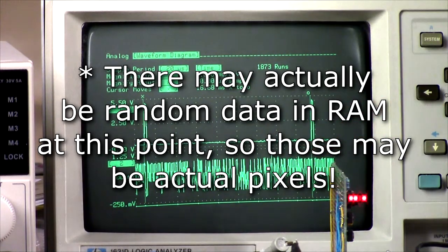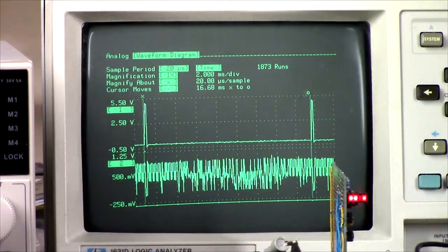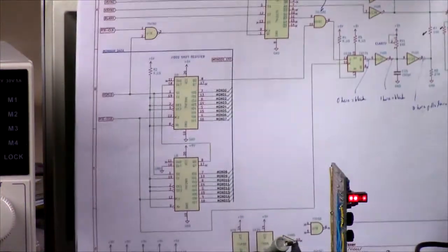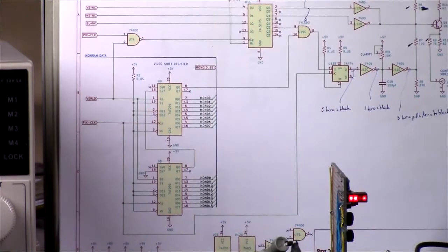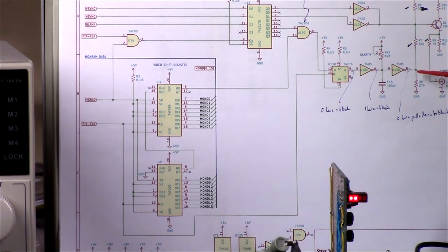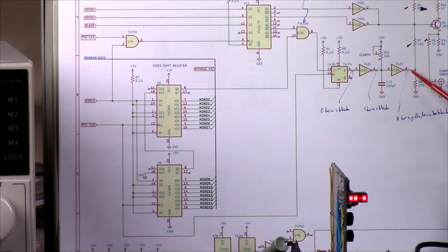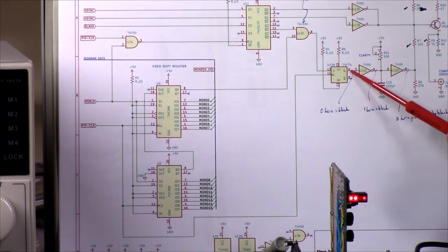Okay, speaking of black and white levels, we should be at black level, we're at white level. Why is that? Let's go back to the schematic. See that? Okay, let's see. This is 0 here pulls down to black level. So black would be a 0 here, which that's an inverter. So that means it's a 1 here. That's an inverter, which means it's a 0 here.